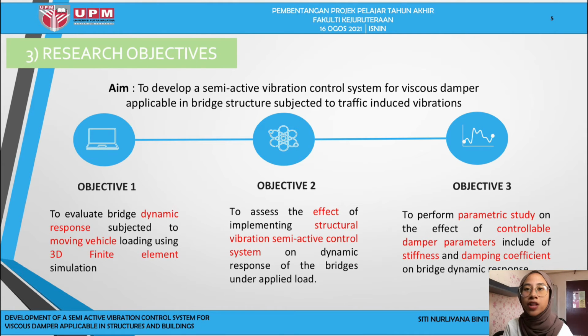Firstly, to evaluate the bridge dynamic response subjected to moving vehicle loading using a 3D finite element simulation. Secondly, to assess the effect of implementing the structural vibration semi-active control systems on the dynamic response. And thirdly, to perform a parametric study on the controllable damping parameters such as the damping coefficient and stiffness.